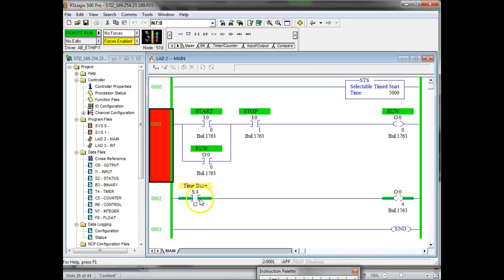So this is being selected by the time base, and you pick out a bit, whichever bit comes closest to what you want, and you can OR them together, or AND them together, to get a more precise time if you needed a real precise time on that. So what's that in? That's in the status register. Word 4, right?